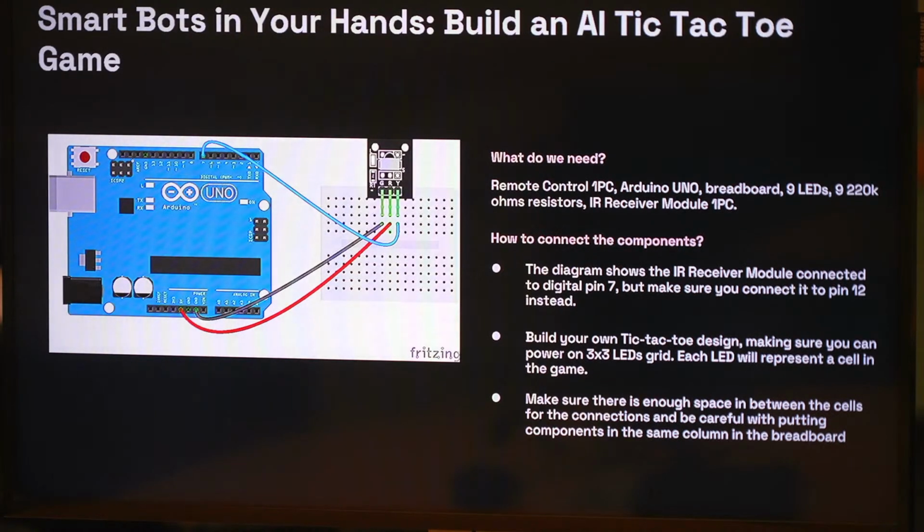So we copy pasted the code that you uploaded, and we're unsure if we're supposed to press something to make it work. I see first it's missing all the digital pins for the LEDs. Oh, sorry. So what are the digital pins? Digital, from 2 to 10. So this should be 2 all the way to 10, like here on the positive.